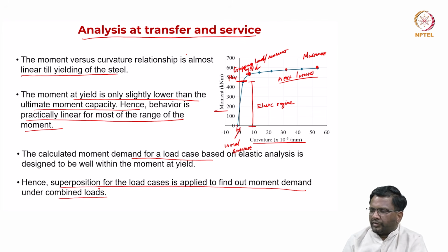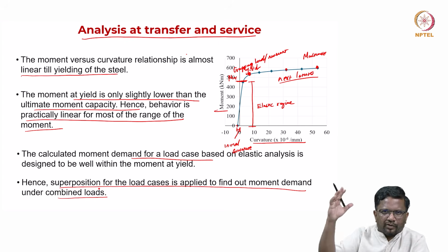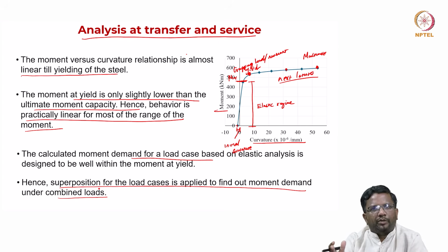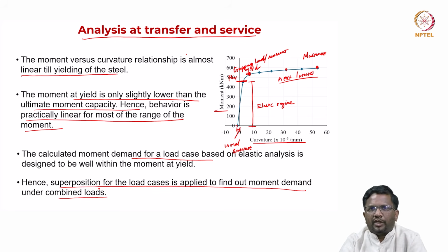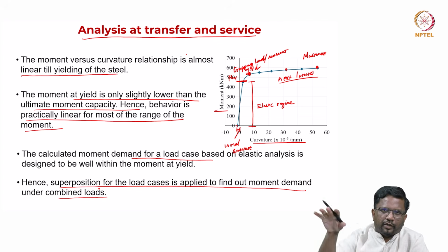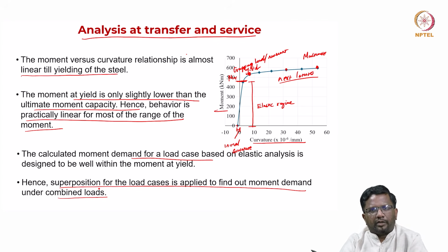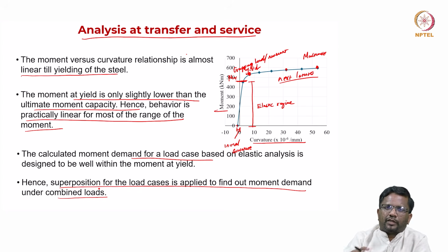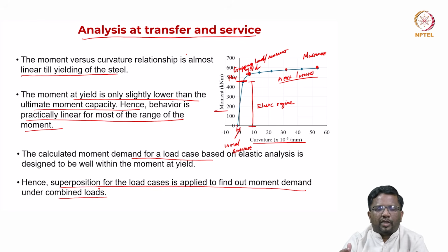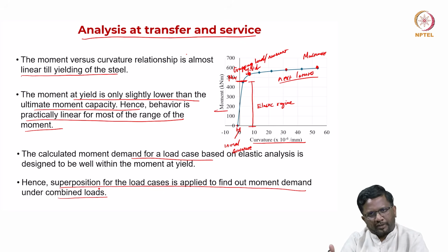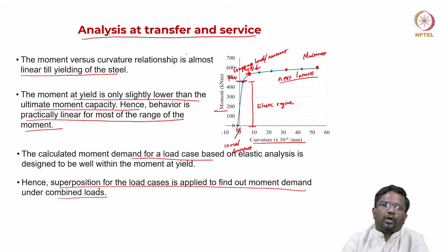You see here, in this way, when you do elastic analysis, actually for structural analysis, typically in design, we do linear elastic analysis, we estimate the demand. And when we do the ultimate strength calculations, we actually do inelastic analysis by assuming that stresses and strains are going to exceed the elastic limit. In that way, capacities will be calculated in a conservative way. When you do elastic analysis, the demands will be estimated slightly in a conservative way. In both ways, demand is estimated in a conservative way, capacities are slightly underestimated. In that way, you get overall better factor of safety in your design.